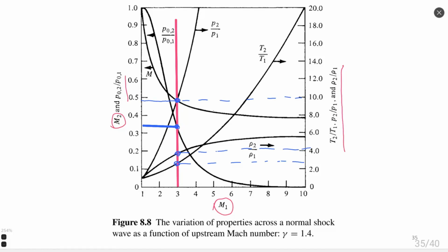When we increase Mach number, we see drastically decreasing efficiency. For example, already for Mach 5, our efficiency will be maybe close to 5%. So we will lose on transition on the normal shock wave 95% of energy. This is absolutely not good.